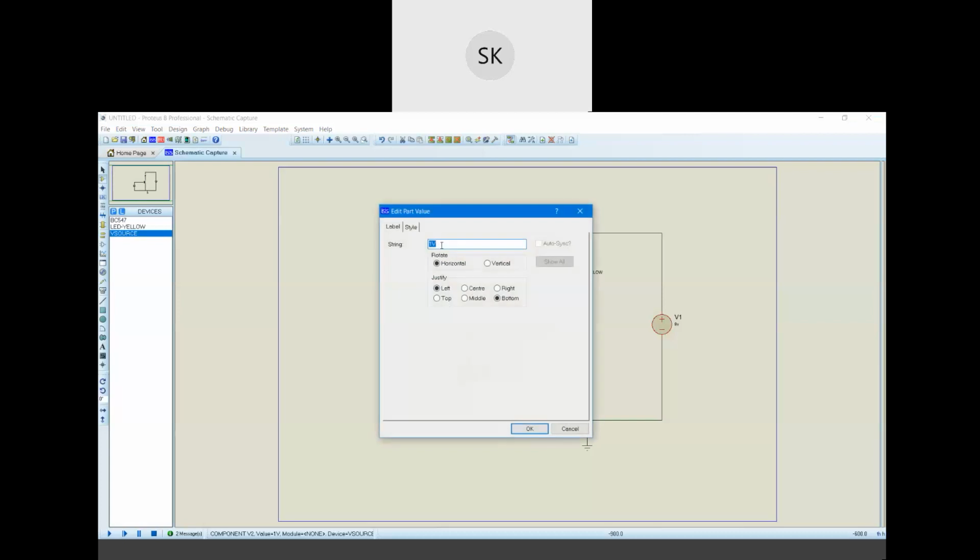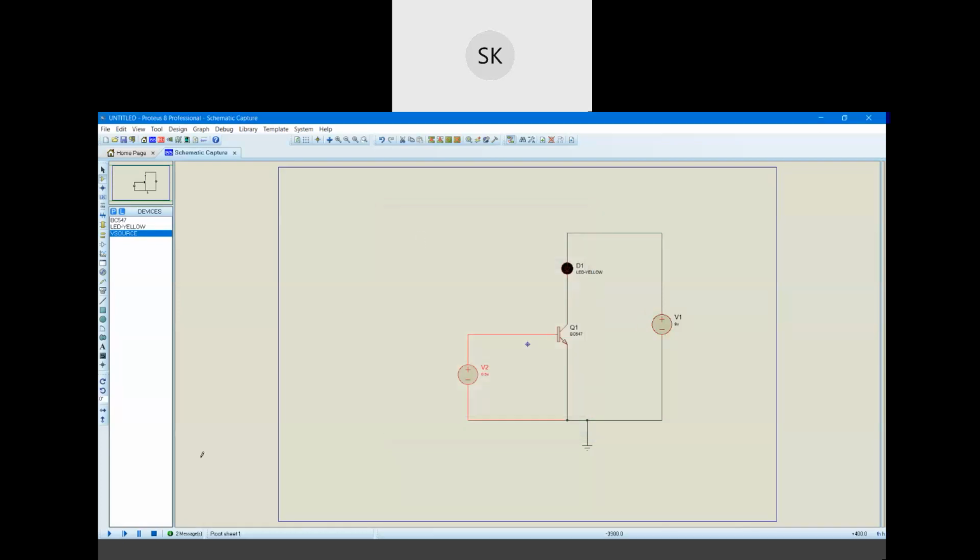First of all, we will select the amplitude as 0.5 volt and then run the circuit. You can see that for 0.5 volt, again the LED is off. Hence, it shows that when the sensor is in a free state, that is when it is not getting any stimulus from the environment, the circuit acts as an open circuit. The current will not flow and hence the indicator also won't glow.